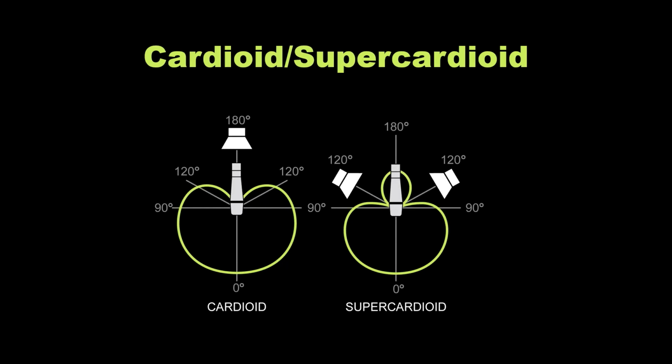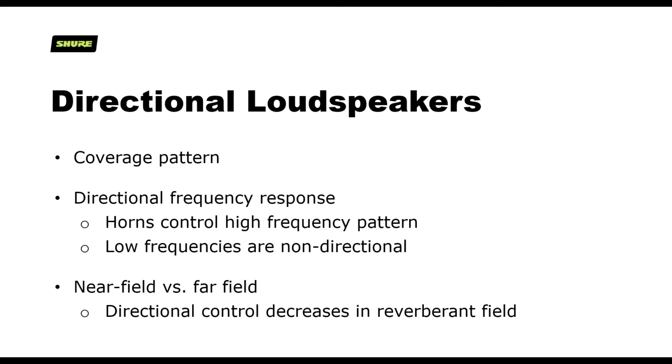In fact, we used to include, maybe we still do, I haven't looked in a while, a little protractor type template thing that came with the mic that fit over the grill. So you put this little cardboard piece over the grill of the mic, and it had arrows showing you essentially what we're looking at here, which is where to place the loudspeakers when you use a supercardioid pattern microphone. So again, going to directional components can help, not as much as keeping the mic closer to your mouth, but just make sure you're placing your loudspeakers appropriately.